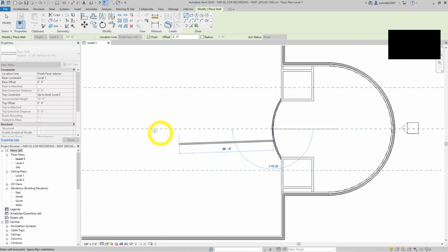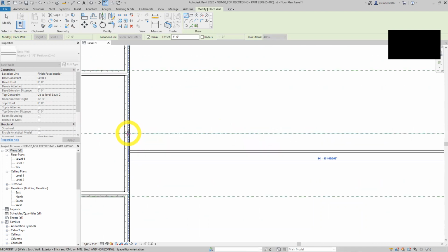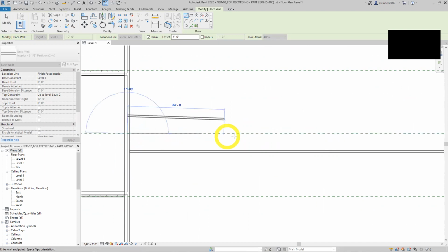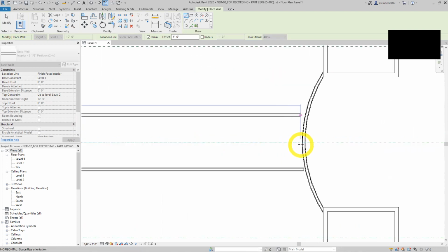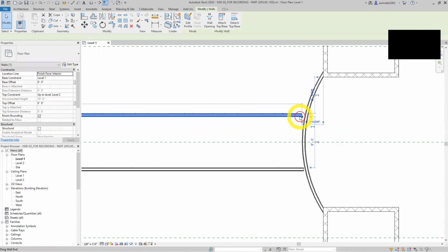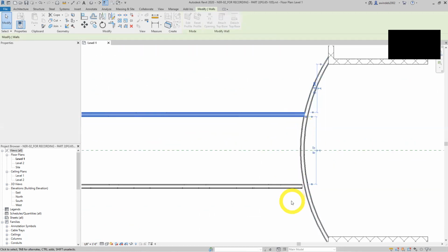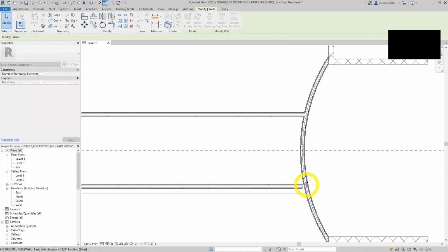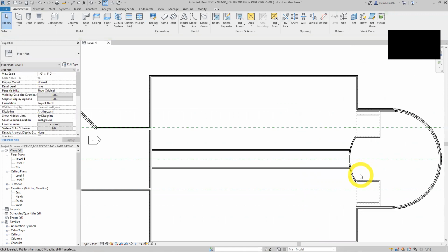If you didn't see the midpoint, that's where we started. And we'll go to the left. We're going to keep this command active as we go. Let's go to the midpoint of this wall, and let's continue on. I didn't leave the command, I'm continuing it. I'll bring it right about here, and we hit escape twice. Now we're going to use our grips for a little bit of power here. Drag wall and grip in the middle here for now. There we go. We got our corridor started.